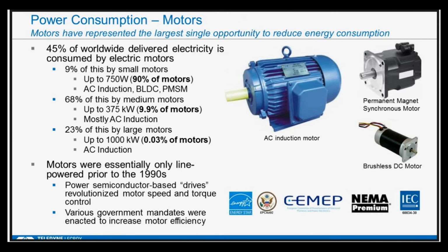Also, motors. Motors consume a huge percentage of the electricity that's delivered, almost half, and it's a tremendously large amount. The bigger motors consume the most power. It's kind of like the 90-10 rule. 10% of the motors consume 90% of the electricity. And those motors are primarily AC induction motors, and they were primarily line powered prior to the 90s. Drives are really a very new thing for motors.